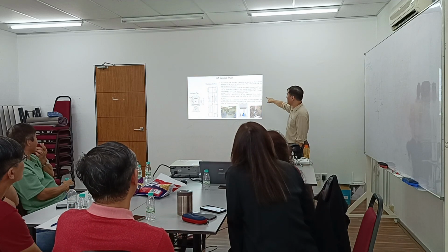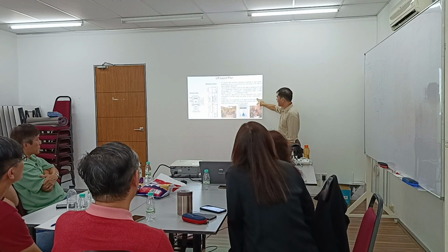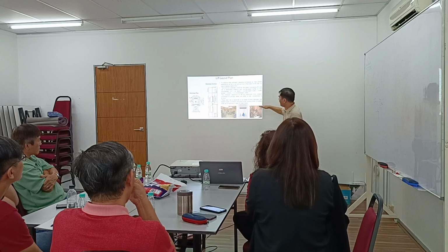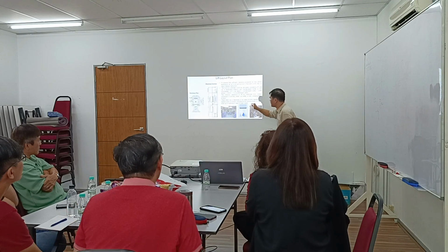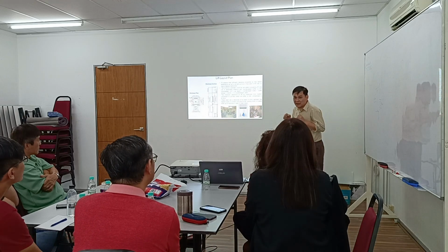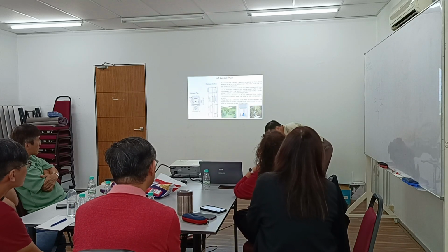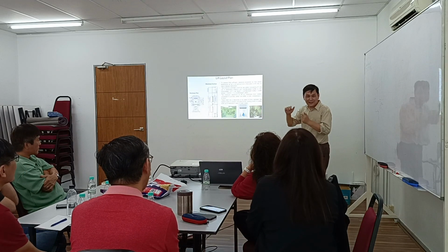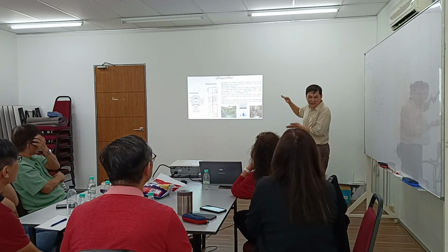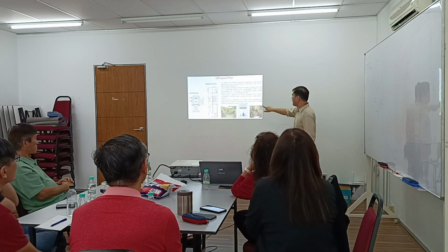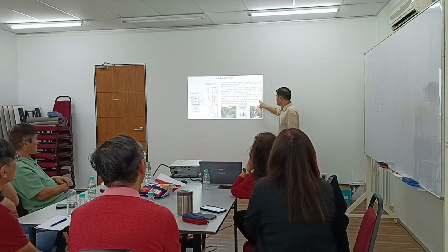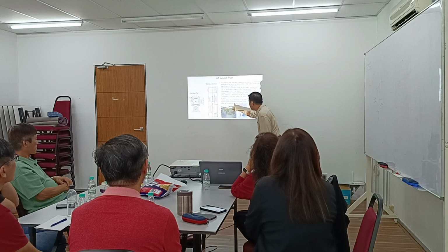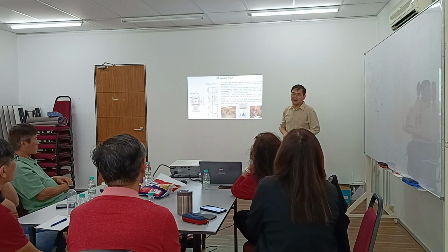Then the minimum clearance at the lift, measured from the bottom cross section. So this is the lift car frame. The lowest point of the car frame to the mid floor is 610 mm. That means the person still can squat below it and still can survive. So that is the reason why they want to specify all these clearances. There shall be a clearance of at least 610 between the highest point of the traction machine and the hoisting hood, to enable hooking up the machine in case of major repair.